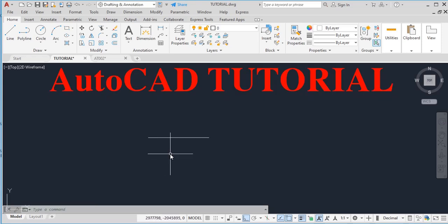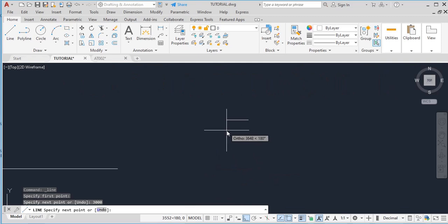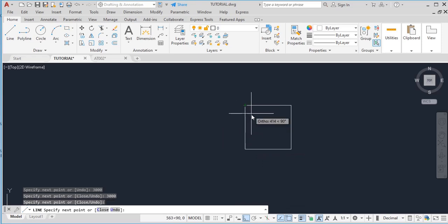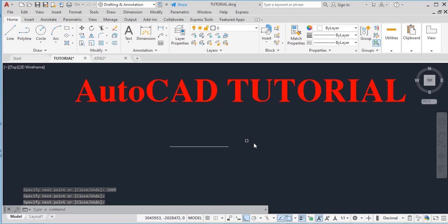Then I'm going to pick the line once again. Draw a line like this by clicking on the first point. Then instead of just clicking at random, you can enter the value of the next point, which is the length of the line. So here I'm going to say 3000 millimeters. Enter. It will establish that line at 3000 millimeters. If you change the direction, you can also use a value to ascertain the distance and click on enter. Then for this, you can just go and connect the line there. Right click and hit enter, or you type enter on your keyboard, so you have that there.